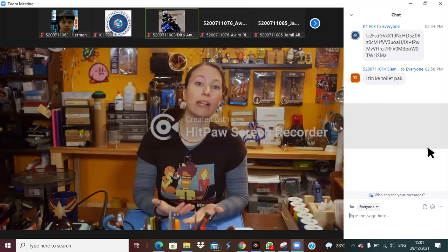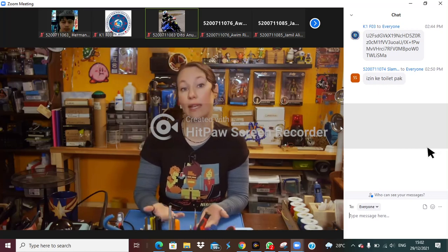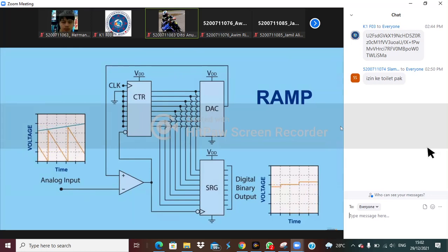With this style of ADC, a free-running binary counter produces a sawtooth wave fed into a digital to analog converter. The sawtooth signal gets compared to the analog input signal, and when the signals match, the corresponding binary number is output, the ADC's timer resets, and the sawtooth starts over. The sawtooth always starts from 0, so the lower the signal, the faster the signals match, but the higher the signal, the longer it takes. This inconsistency in update frequency can be problematic in certain applications.